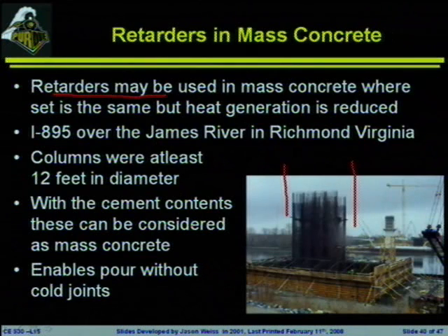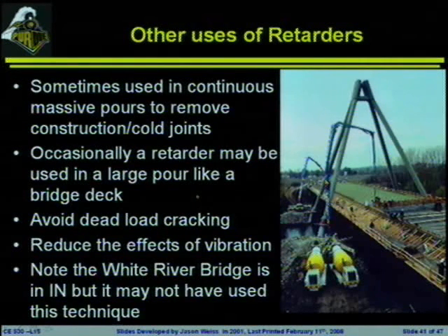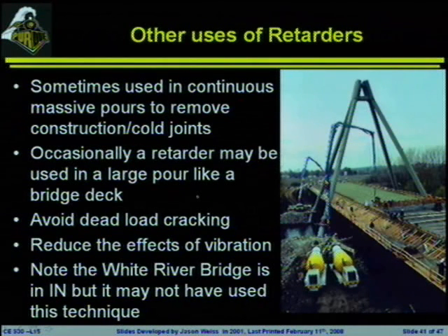It enables the pour to go up without control joints. As I mentioned, sometimes if you've got very complicated construction operations, you may want to try to use a retarder. There's a school of thought out there that believes vibration in bridge decks can cause quite a bit of the cracking that takes place at very early ages. The idea is the concrete is relatively fragile.